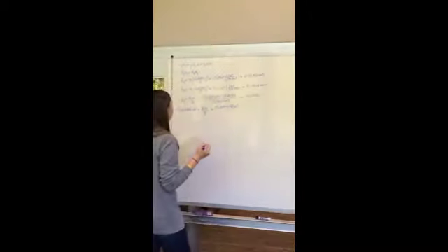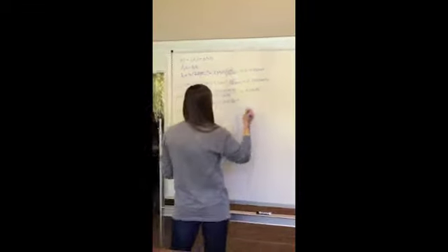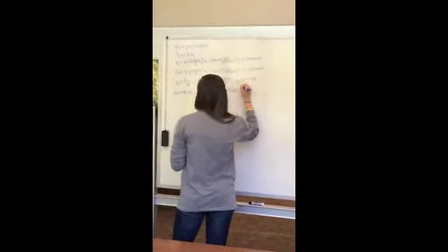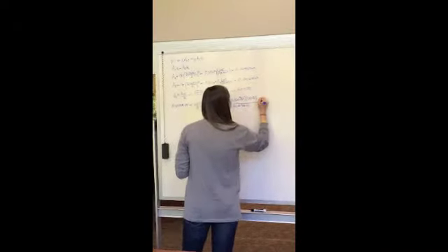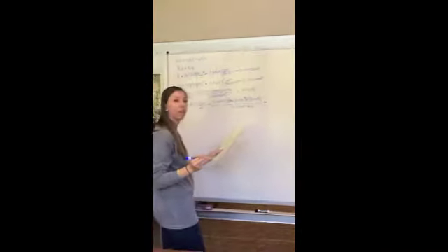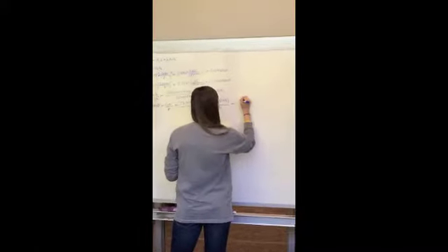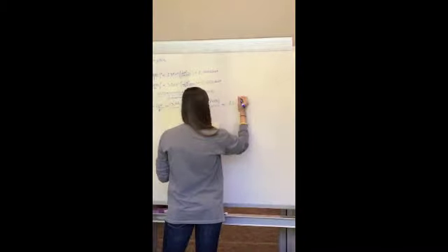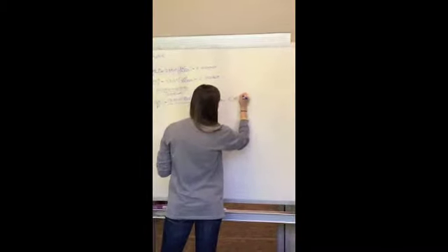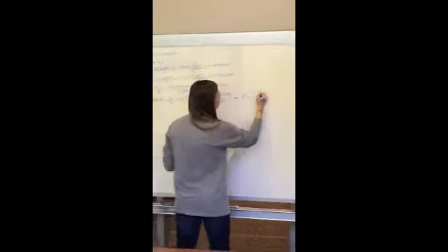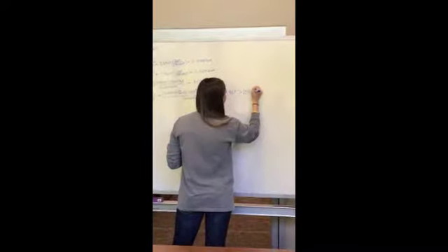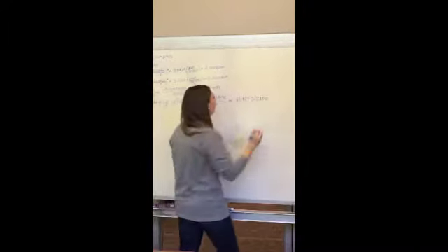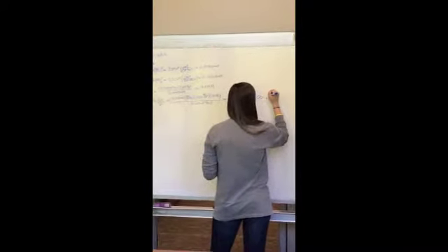And that's converting our inches into meters. And if you plug this into the calculator, you'll get 61,967. So this is more than 2,100, which is the criteria for a turbulent flow. So therefore the flow is turbulent.